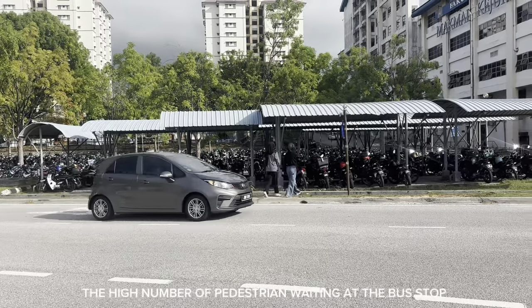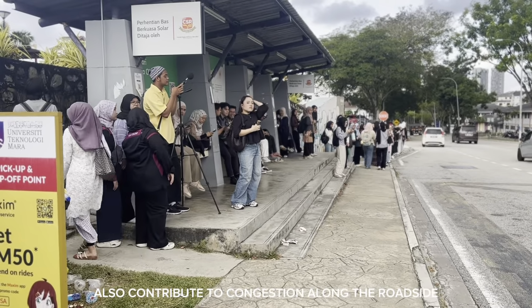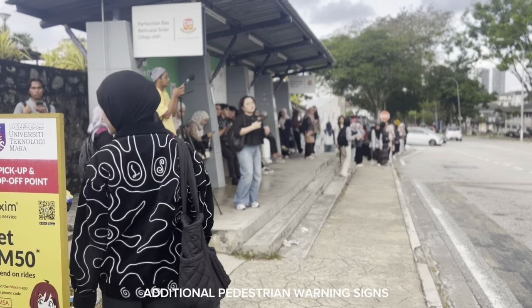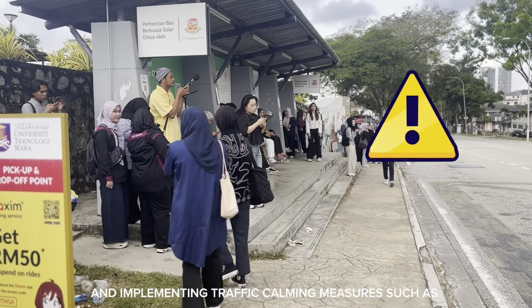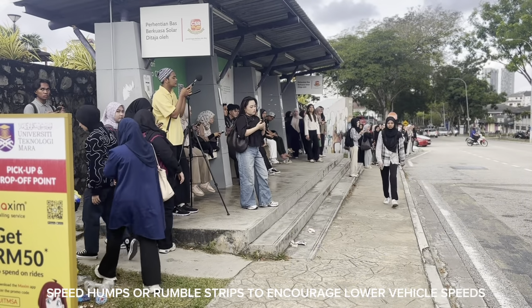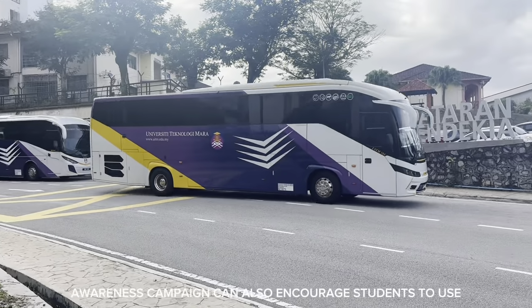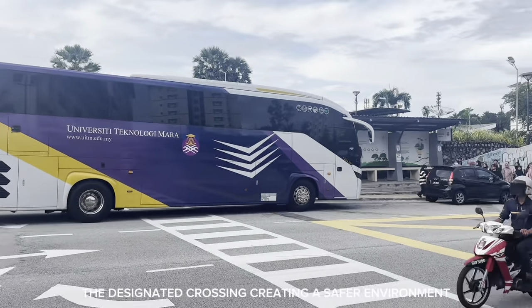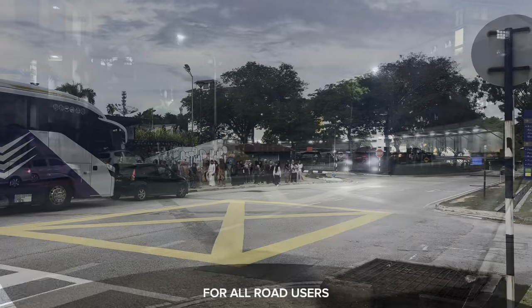The high number of pedestrians waiting at the bus stop also contributes to congestion along the roadside. To improve safety, we recommend installing additional pedestrian warning signs and implementing traffic calming measures such as speed humps or rumble strips to encourage lower vehicle speeds. Awareness campaigns can also encourage students to use the designated crossing, creating a safer environment for all road users.